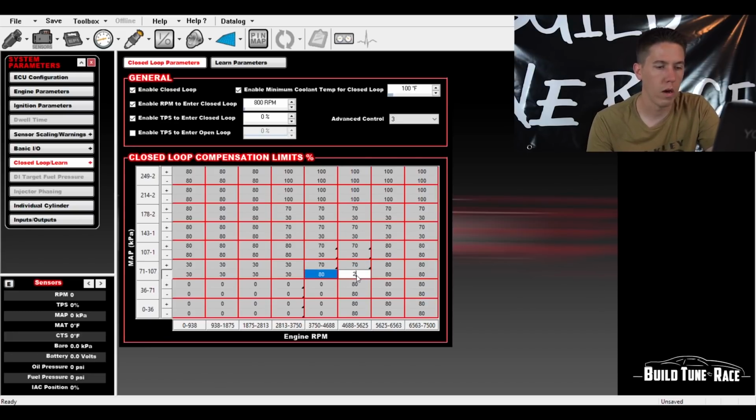30. When you're first tuning in a car, I leave it at 100, and I keep my eye very, very closely on the air fuel. Usually the idle, big cams, a lot of things, you're letting it idle rich because of the way that the injectors are or whatever. I try to tune that all in by hand. Maybe I let it get it close and then shut it off and then go back and adjust to get that real nice, consistent idle air fuel. But otherwise, up through the upper portion, I leave it at 100%, and then I just kind of creep into boost, and I keep a really close eye on the air fuel reading on the Holley. And if it starts going lean at all, I shut it down and work back up to it until it's nice and consistent and it's working well.